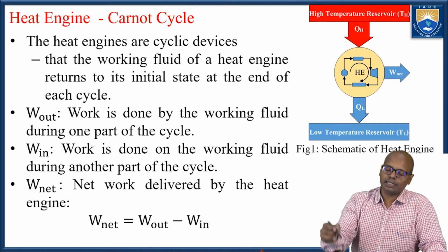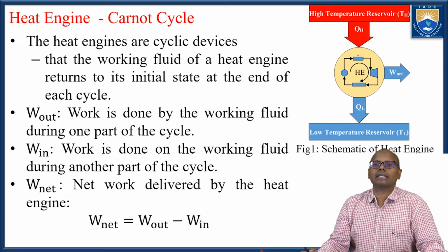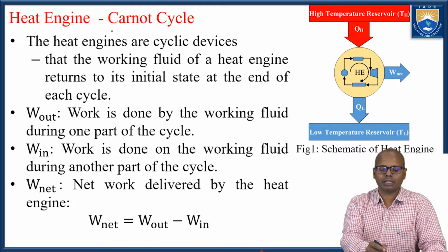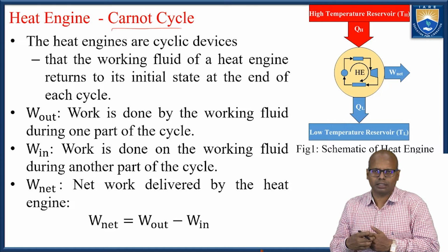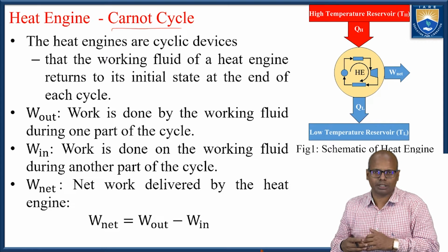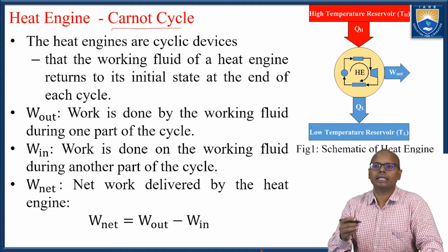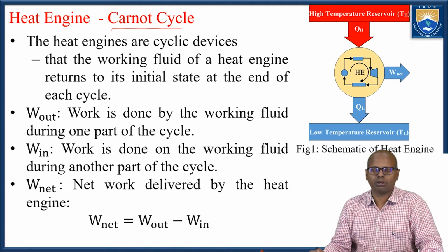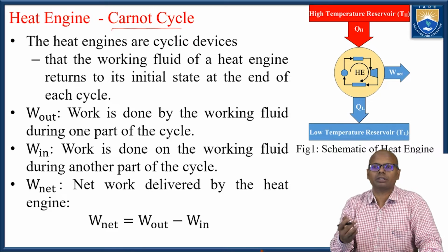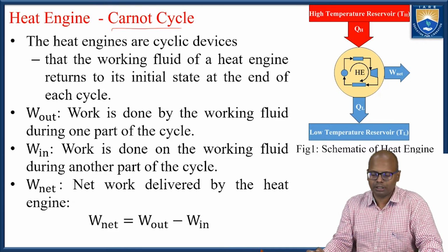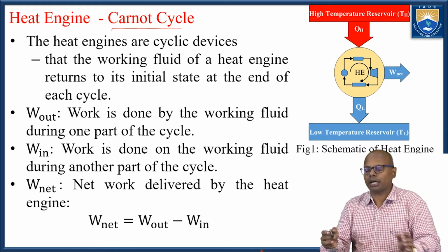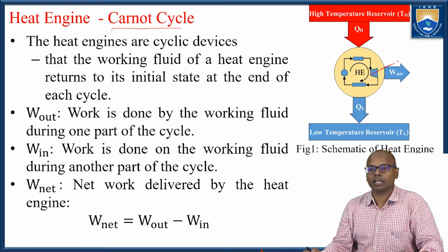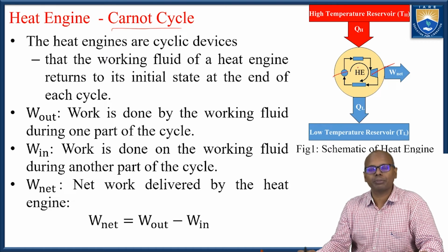Now, I said this undergoes a cycle, and here is one cycle. It is a Carnot cycle. The Carnot cycle is an ideal cycle because all the processes happening in it are reversible. Two processes, constant temperature heat absorption and constant temperature heat rejection, are happening, and two isentropic processes, isentropic expansion and isentropic compression, happen.